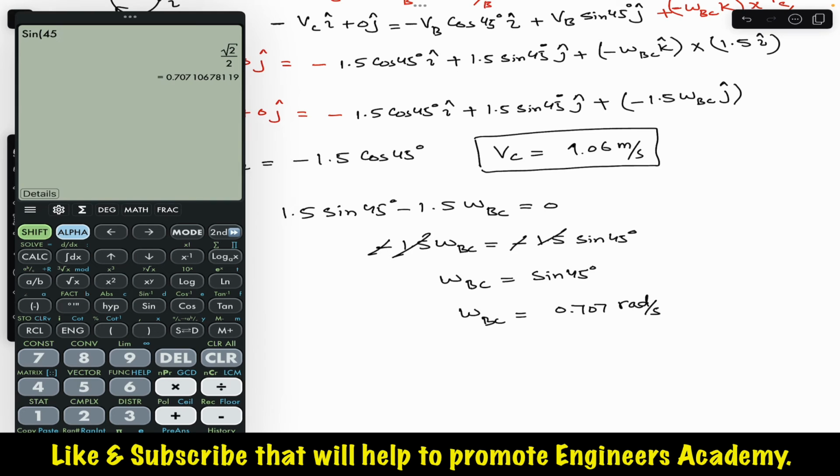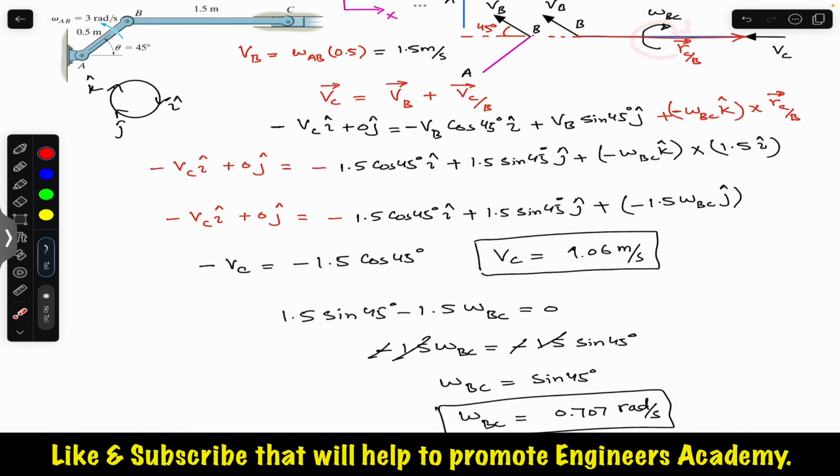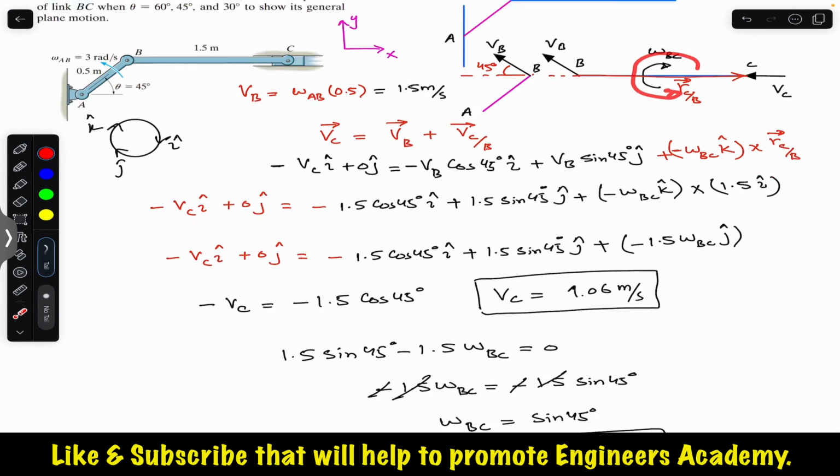radian per second. So this is the velocity magnitude of block C, 1.06 meter per second towards the left. And this is omega BC, 0.707 radian per second in the clockwise direction. Remember, if the answer was negative, then the assumed direction would not be accurate, so we would say that omega BC is in the opposite direction.